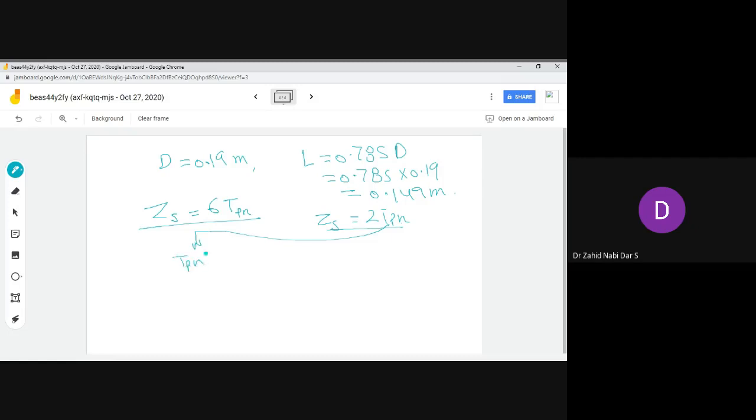In order to calculate T phase, we have Es is equal to 4.44 f phi m Kw into T phase. Now, if we want T phase, T phase is equal to Es divided by 4.44 f phi Kw. So Es we have, 400.